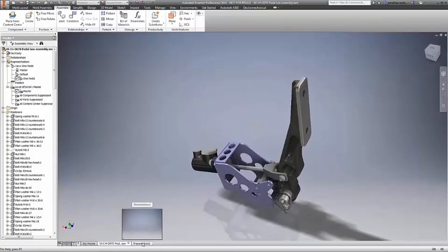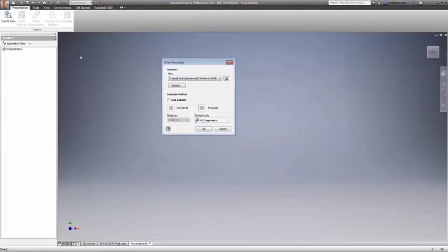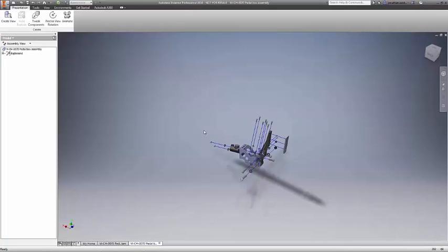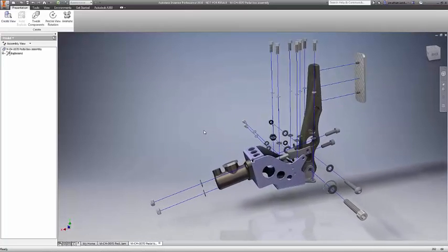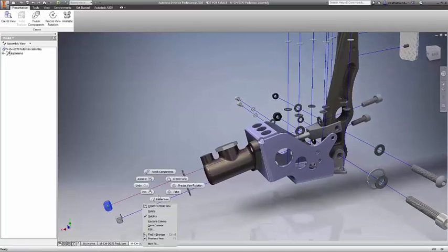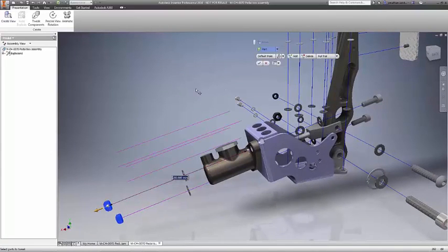When using Auto Explode inside 2016, you now have more options to get the desired view and get it fast. Whether you decide to explode one level deep or all levels, do so in one quick command, and even better, you can now decide to include the trails for all components, all parts, one trail for each tweak, or none at all. Furthermore, each tweak Inventor creates for the Auto Explode becomes its own editable tweak, so you can edit or delete each one individually and fine-tune your view to perfection.